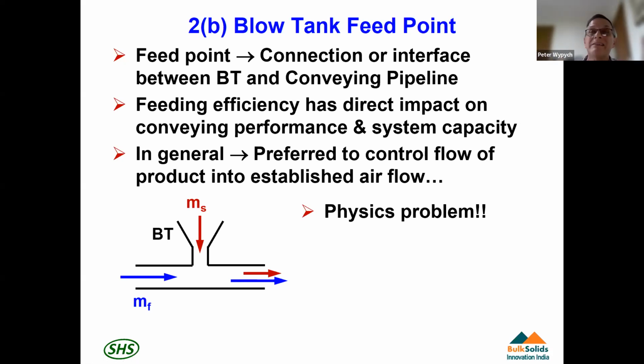It's actually a momentum balance problem. If you consider the mass and or the density of the product and its velocity, that's momentum. And once you have a certain feed rate and it coming out at a certain velocity due to gravity, then you need a certain momentum of air to balance that, to make sure that you can move that product in the direction that it needs to go.